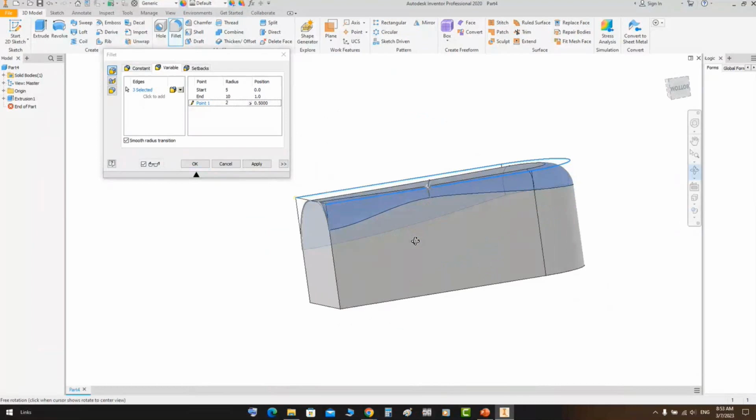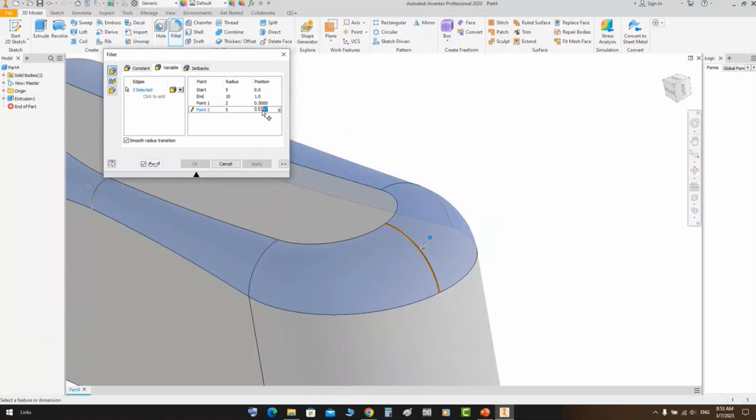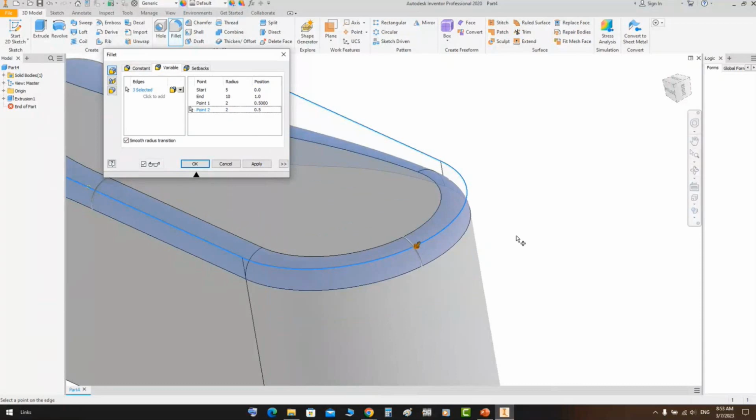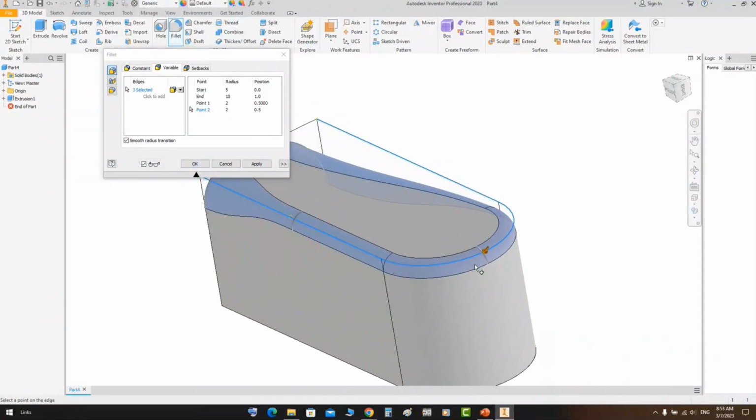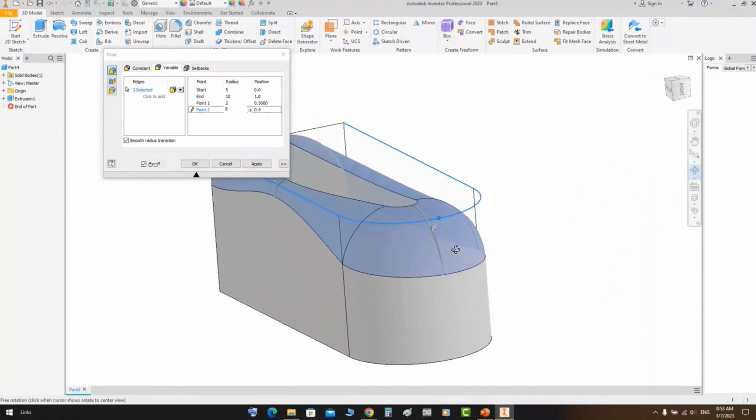Now if you would like to make another fillet here at the middle of this line, click here on this form and select that value. Let's make it at the middle of the arc. And you can set the value at this point. Let's make it 2 millimeters at this point. So from here to there, it will be 2 millimeters, or you can increase it, let's say, up to 8 millimeters. So you will get 8 millimeters at this point. It will be like that. So from 2 to 8.